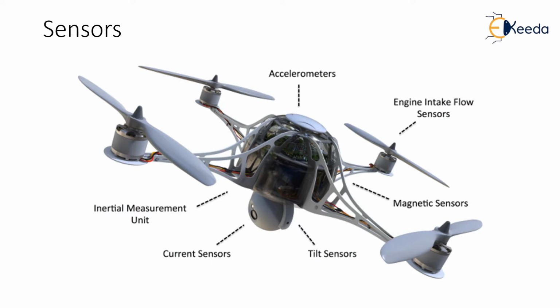MEMS accelerometers sense movement in several ways. One type of technology senses the micro movement of very small structures embedded in a small integrated circuit. The movement of these small diving boards changes the amount of electrical current moving through the structure, indicating a change of position relative to gravity.